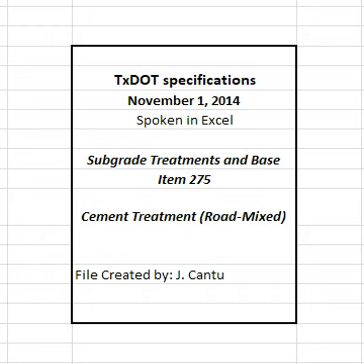Adjust operations as required. Begin rolling longitudinally at the sides and proceed towards the center, overlapping on successive trips by at least 1/2 the width of the roller unit. On superelevated curves, begin rolling at the low side and progress toward the high side. Offset alternate trips of the roller. Operate rollers at a speed between 2 and 6 miles per hour, as directed.